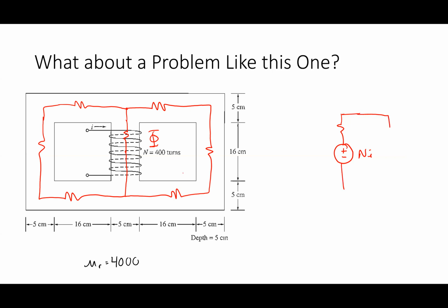If I have three reluctances in series like that, what do they become? One reluctance. So if I wanted to solve for the total flux here, I could do KCL, or I could say I've got this reluctance and that reluctance in parallel with each other, combine those, and take whatever approach I want to get that phi value. The phi is the flux going through the coil itself. I don't care what the flux is through these other legs. I care what it is through the center leg, through the coil.